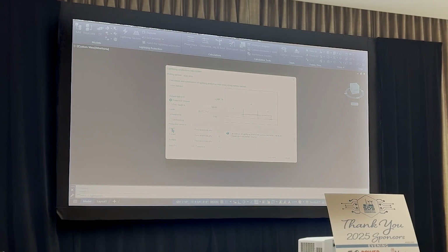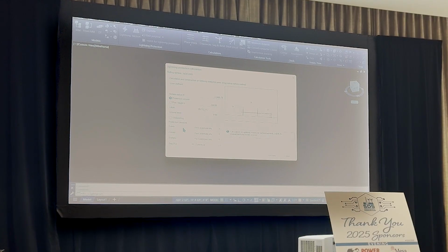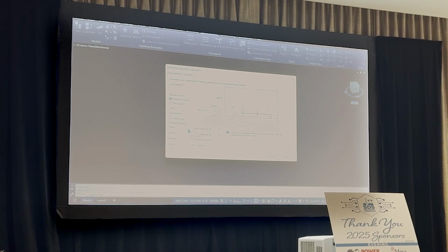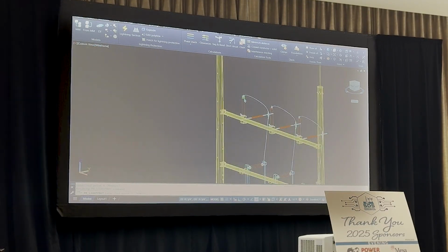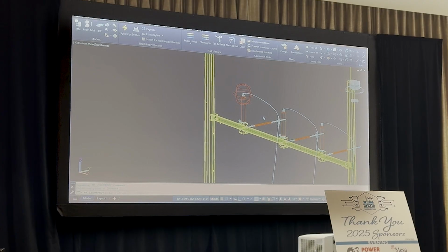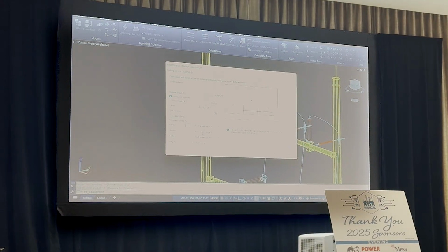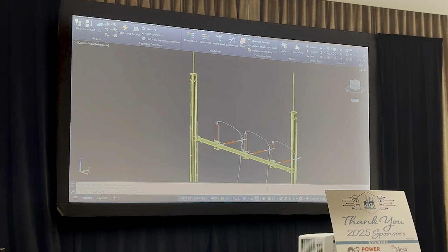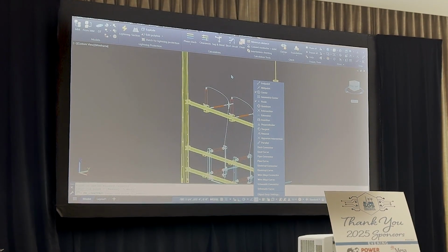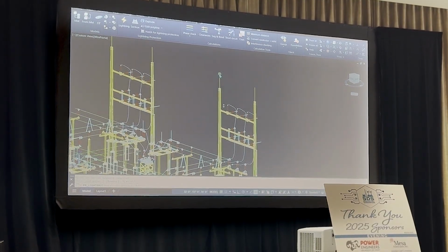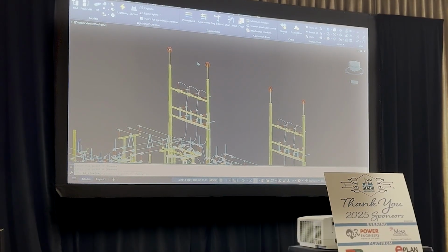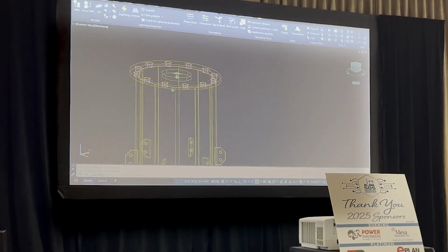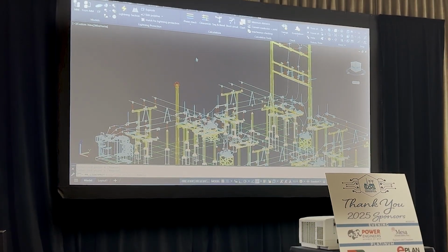And then at this point, all you need to do is tell it what items to use. This one already has some things designated. If I hit edit rods, you'll see that these are designated. To add another rod, you just click another item. So that's how you add rods. I'm going to remove all of them, and then add another one. If I have certain types of work points on the top of my structure, called a lightning protection point, they'll auto find, and I can hit find automatically. They'll all pop up. So I have these guys. Put one here too, and then here.